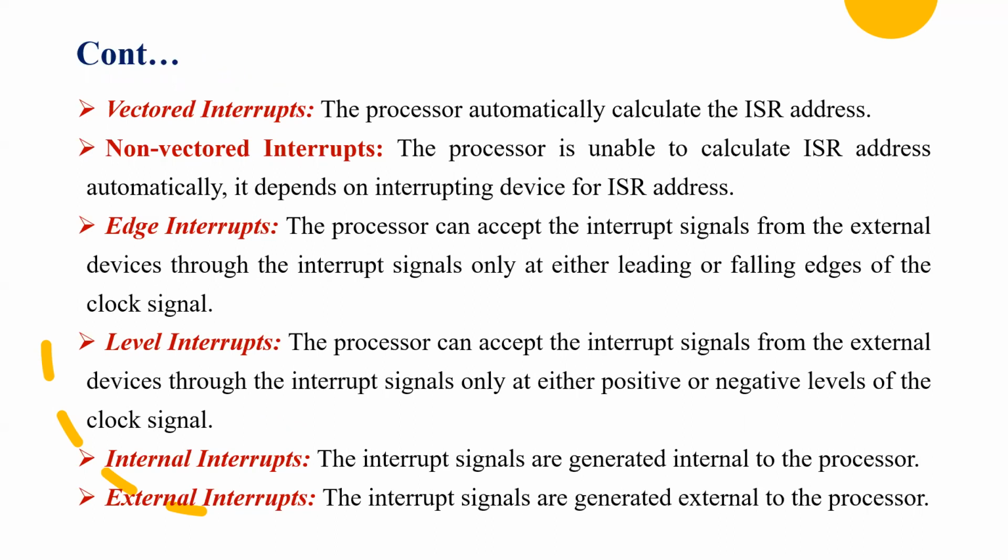The second type is non-vectored interrupts. If you want to call an interrupt non-vectored, the processor is unable to calculate a service routine address, that is ISR address, automatically. It depends on the interrupting device for the ISR address in order to provide a service for that interrupt.